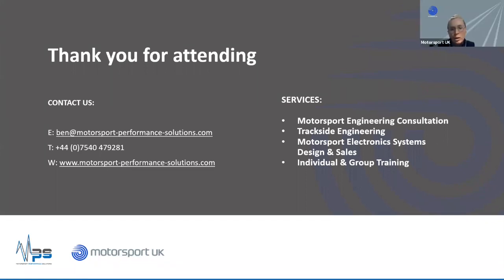Perfect. You may have answered this one in the braking section, so if you have, we'll move on. On monitoring brake pressure, would you use two sensors if you have separate brake cylinders for front and back? So again, yes. If your budget's there, that's what I'd do. All the professional customer cars do that.